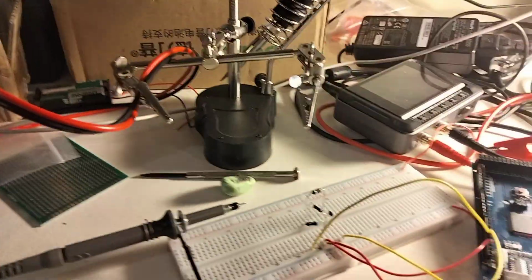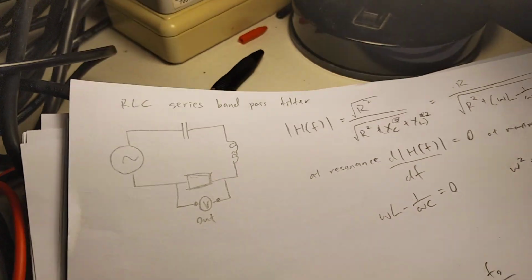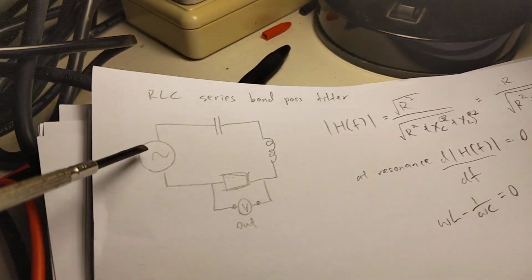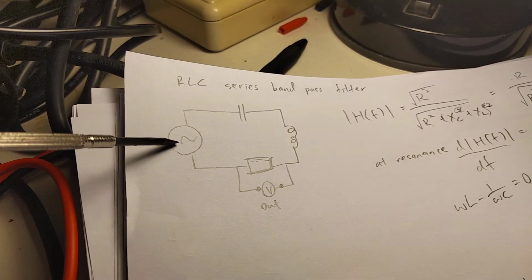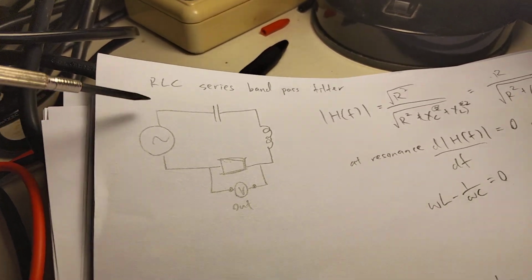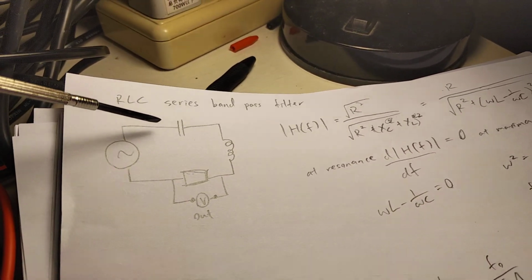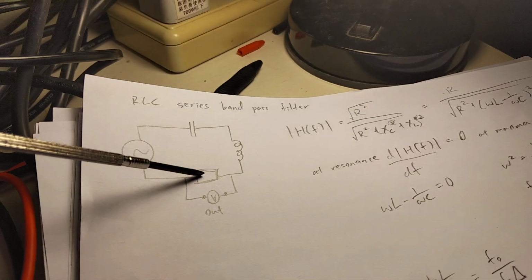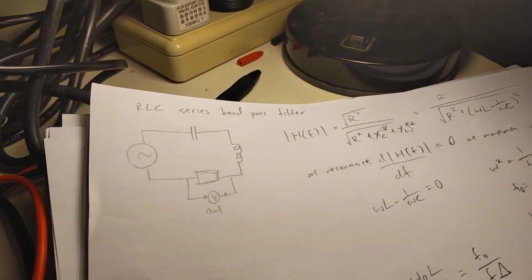So basically, how it works is there's a signal source, which is this little wiggly component here, and that's the Arduino output PWM pins. So it's outputting square waves, and then I'm using an LCR filter, so a capacitor and an inductor in series with a resistor, and I'm taking the voltage out of the resistor.